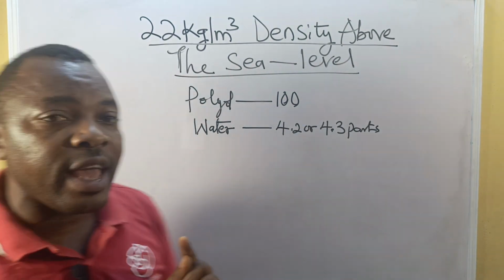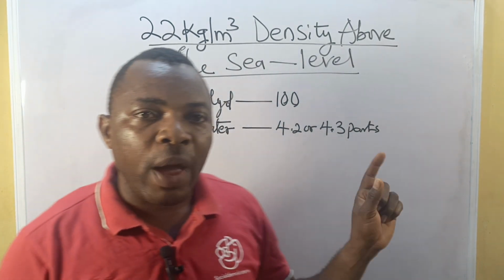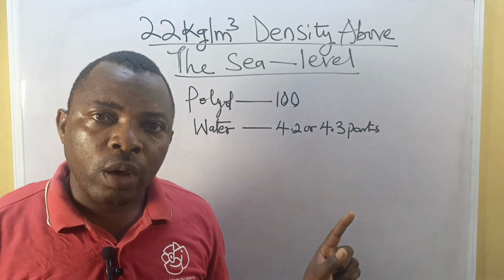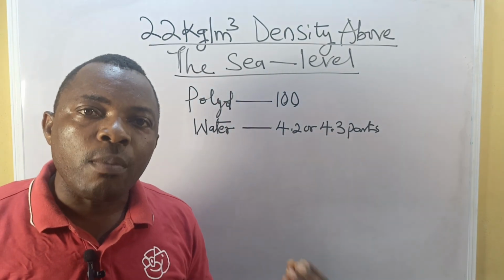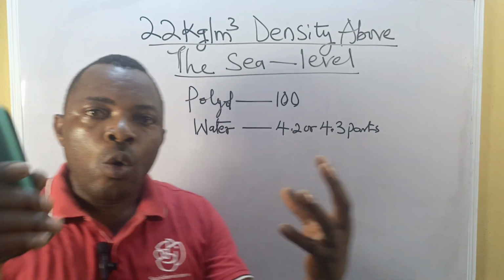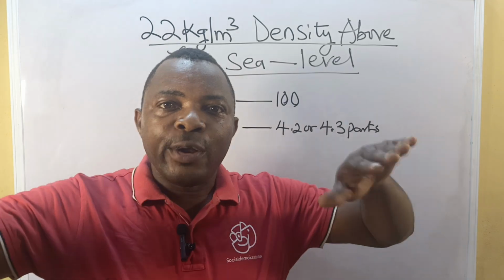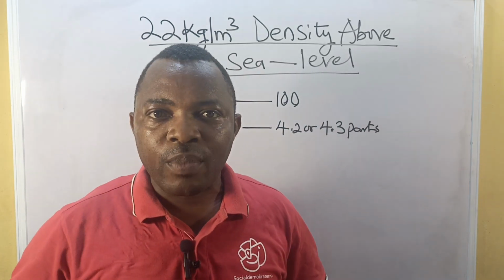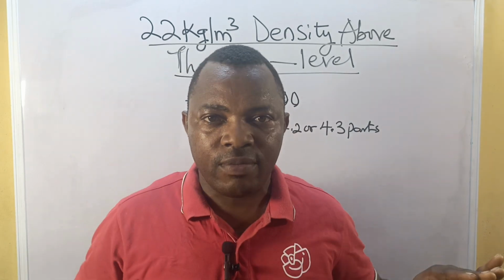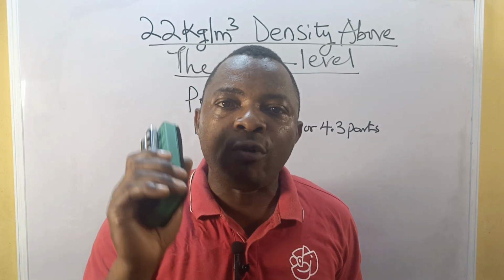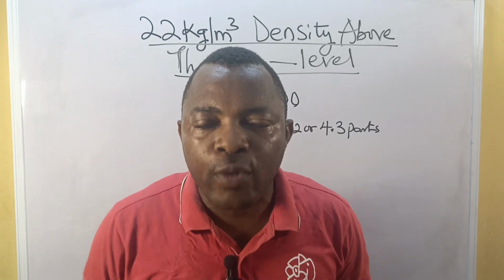Now I can also say in Nigeria, I'm using parts per 100 of polyol of water 4.8, and I'm also achieving a foam density of 22. When I say this, I understand that the air pressure at these locations is not the same. But if we assume we are running it at sea level, we will all use water of 4.55 to achieve a foam density of 22.